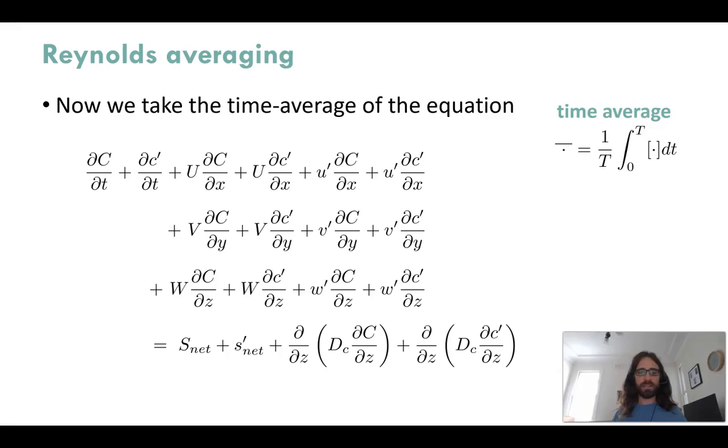And the next step in our long process is to take the time average of this overall equation. So what we can do is apply a time averaging operator, which is equivalent to putting a bar over all of the variables. And if you apply this operator to the entire formula, it's the same as applying this operator to each individual formula, because these properties commute within the addition terms of the equation.